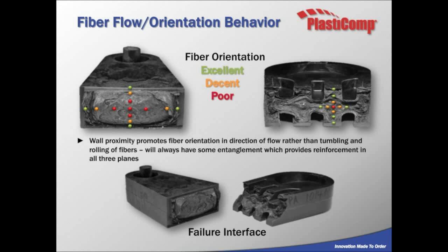Now, the challenge here was that it took a long time to cool off. When we're talking about a molding cycle, because of that thickness, it takes longer to cool. And you also have a lot more internal stresses happening. We can also see what that's doing to the fiber orientation at the core of this part.